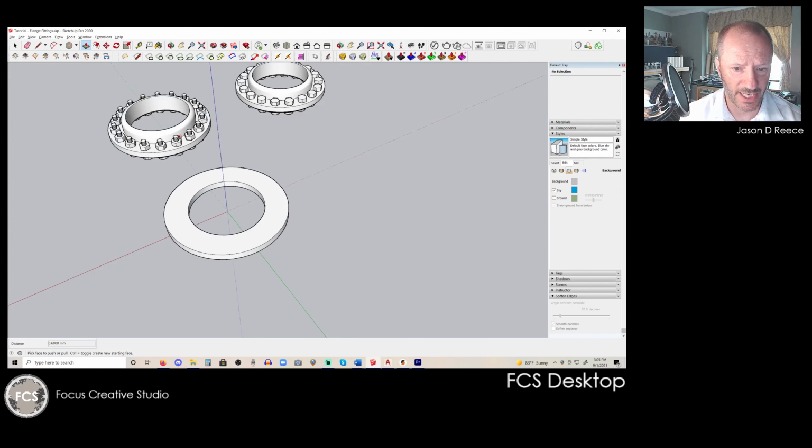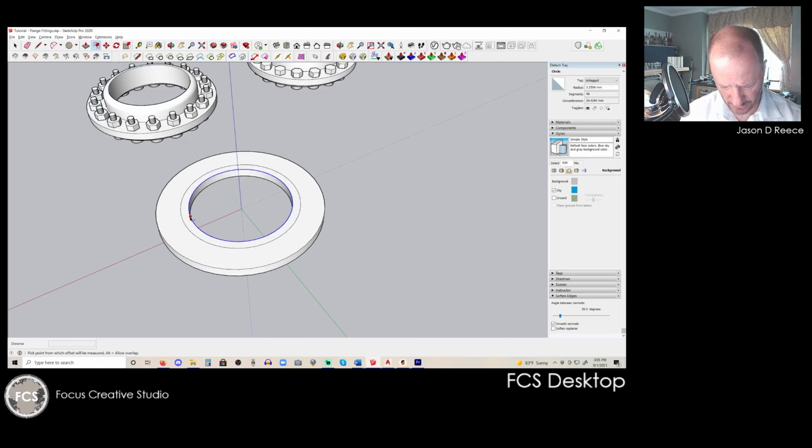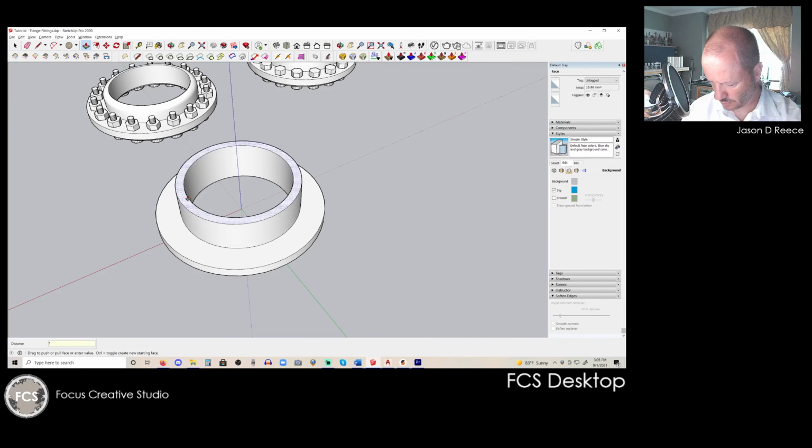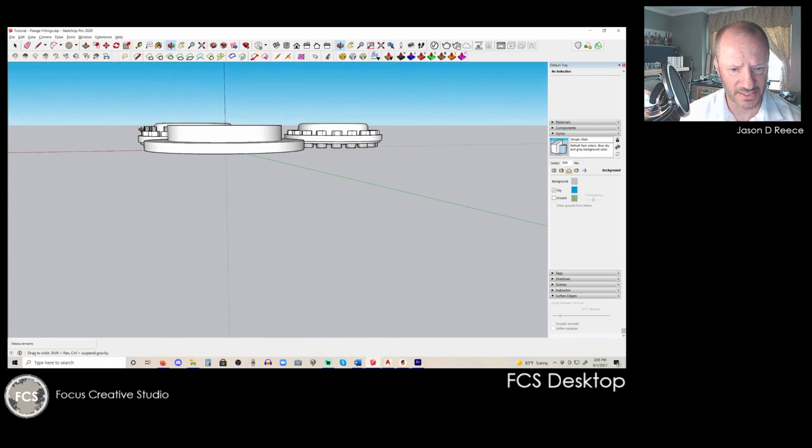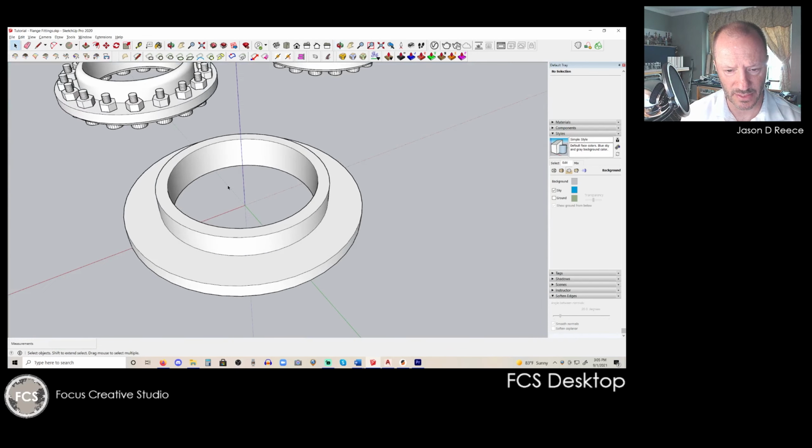We're going to go ahead and create this sleeve on the inside, and we're going to add some detail, even one more beyond what we have here. But we want to offset that 0.5 millimeters. We want to push and pull that 1.2, and that gets us the same as where we're at on the other example.